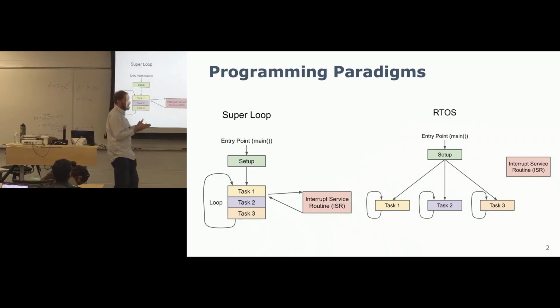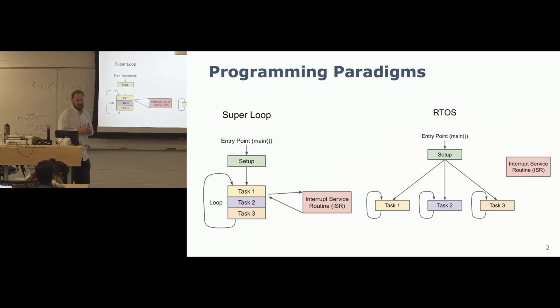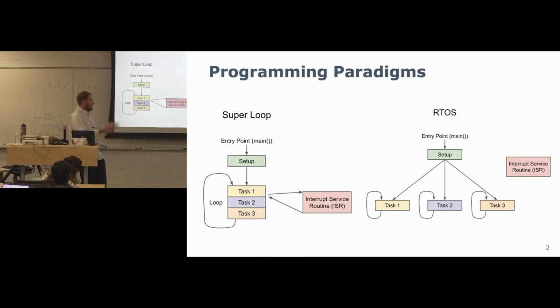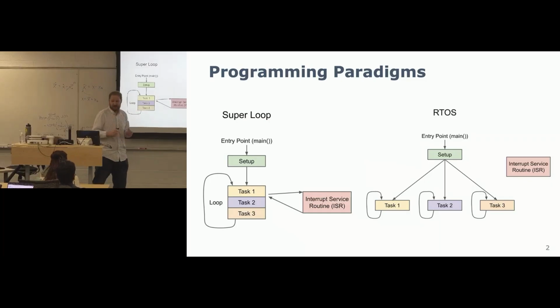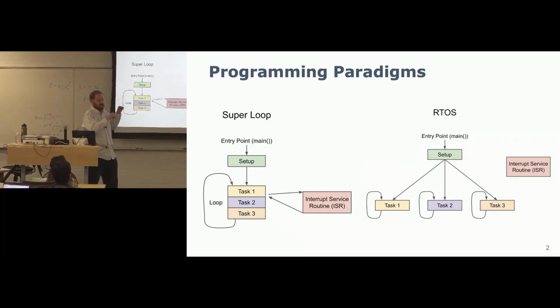And then the STM32 is okay. I mean, you're running at like 120 megahertz anyways, so that's a reasonable processor where you could have so many things going on that you might want to have an RTOS. And built into Cube IDE is a FreeRTOS. It's literally called FreeRTOS. You can push a button and instantiate one. You'd have to really have a good reason to enjoy that much pain in your projects.